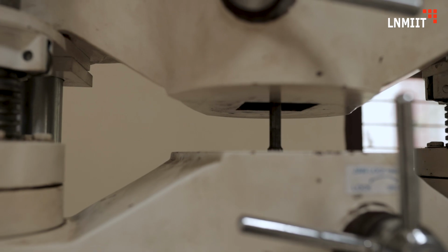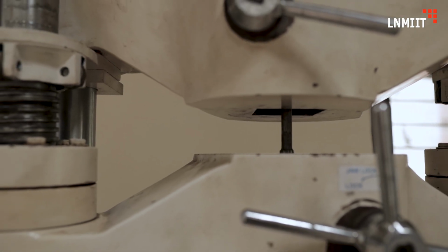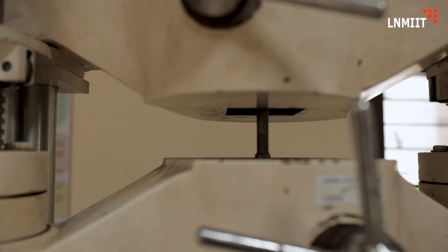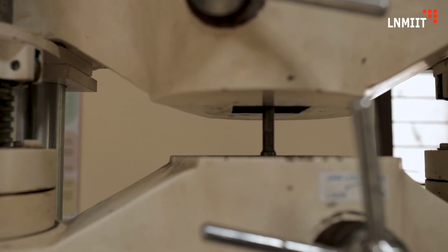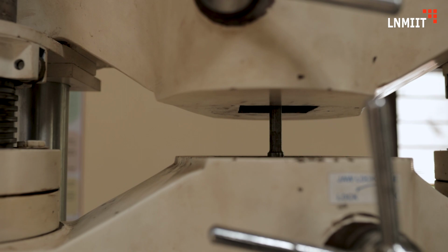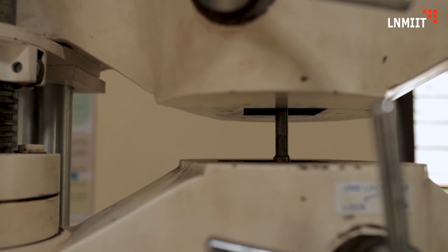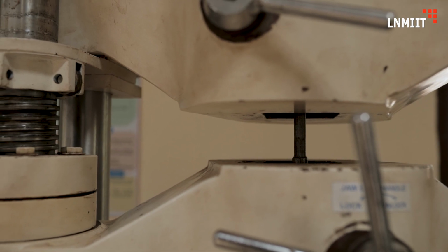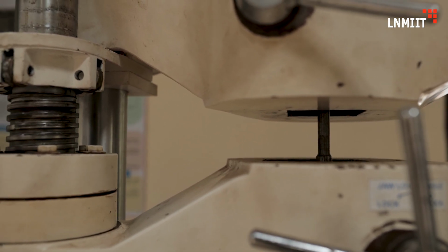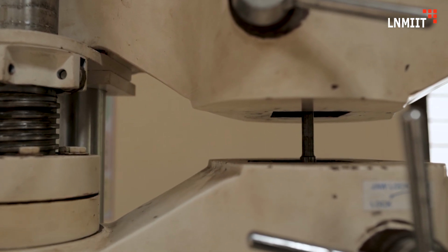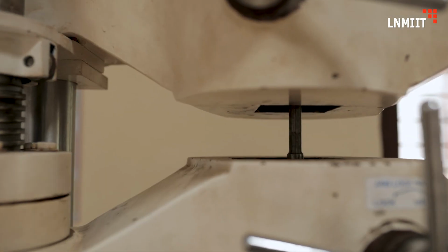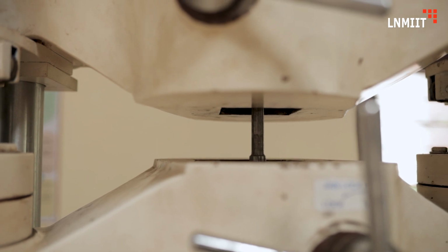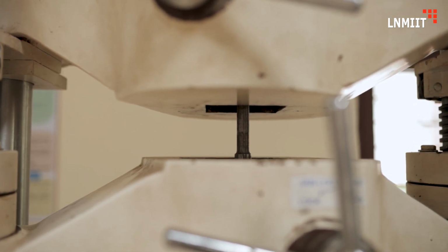As it is a ductile material, a mild steel specimen, there will be a cup and cone type fracture. Once the fracture takes place, we will determine the percentage elongation and the percentage reduction in area. With the help of these two parameters, we may find out the ductility, which is a very important property of the material. We may also find out how ductile this material is.